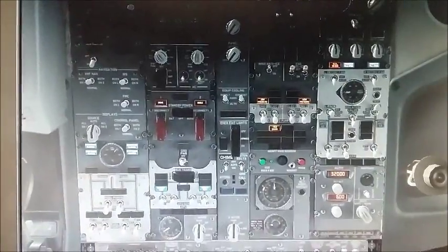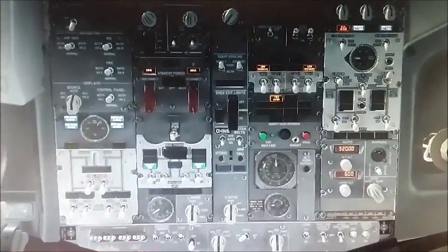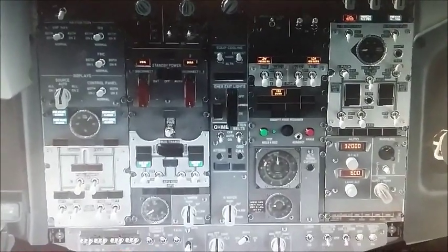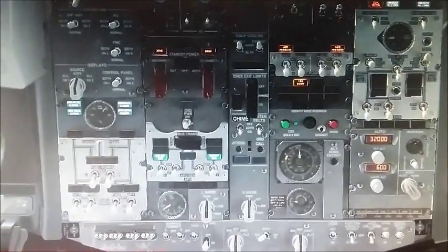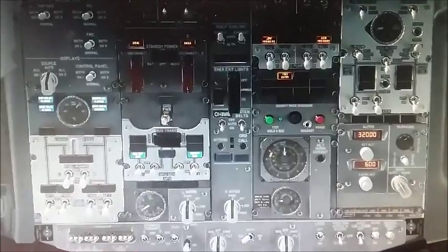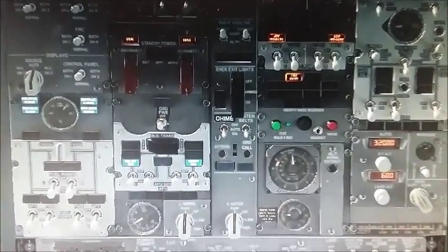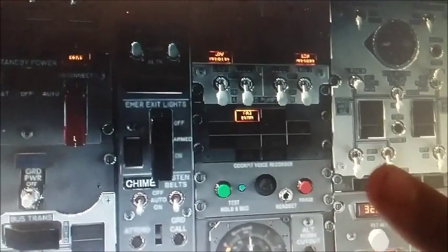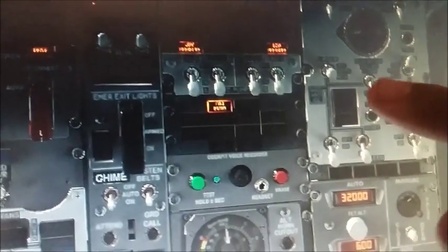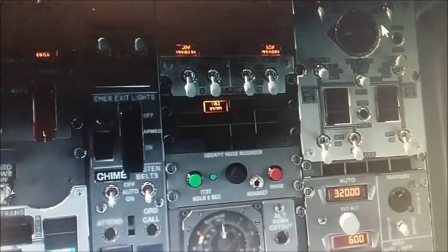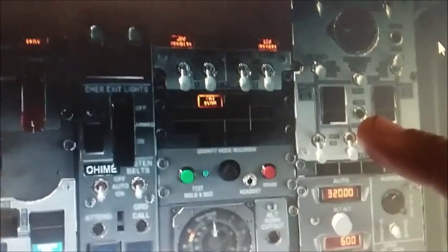Alright, now this is the overhead panel. Now, in this product, the PMDG, for some reason, I don't know if it's PMDG itself or my computer, it might be my computer, I'm not sure. But in any case, here's how the configuration goes for this. Bleed air panel: you have the APU bleed valve on, both engine bleed valves on. You can put this in the auto position or in the open position. Doesn't matter. Auto position is preferred.